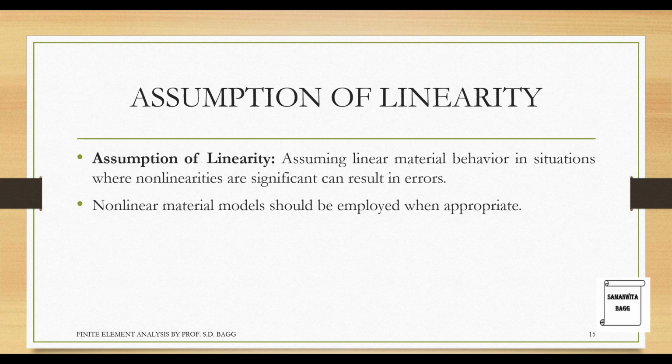Assumption of linearity. Assuming linear material behavior in situations where non-linearities are significant can result in errors. So we generally go for assuming that the material behavior is linear, which is not the correct way of solving. You need to assume non-linearity where it is required. Non-linear material models should be employed when appropriate.